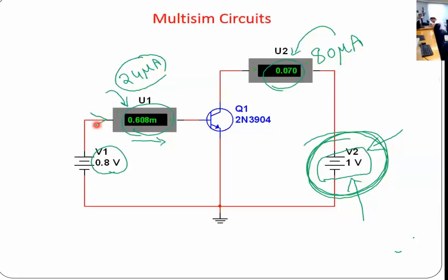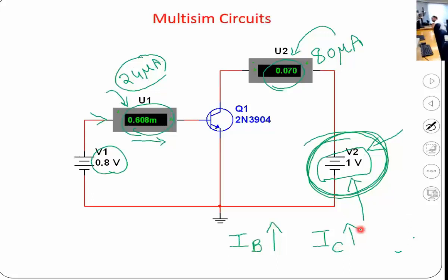As the base current increases, which we usually call IB, an indication for base current, the collector current will increase until you reach a point where it's not going to increase anymore unless you raise your supply on the collector. What's that point? We haven't talked about that point yet. There are some terminologies coming in the next class, but it's called saturation.